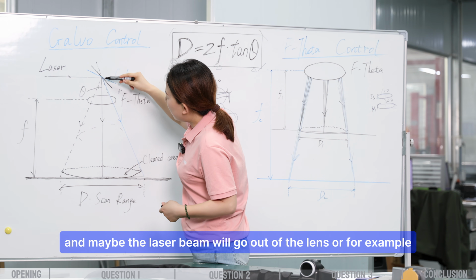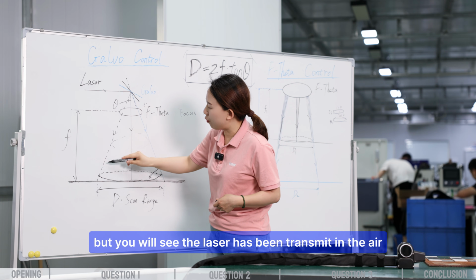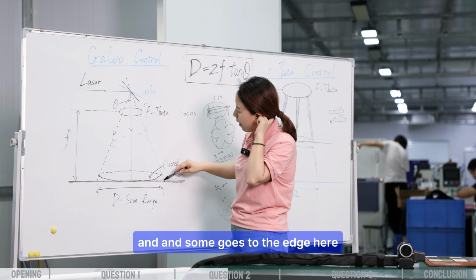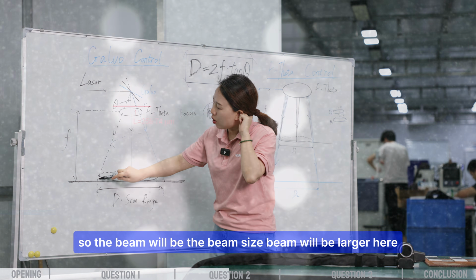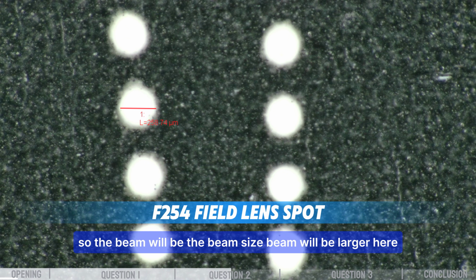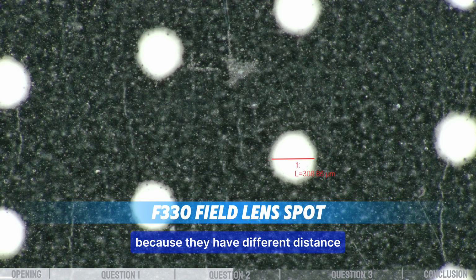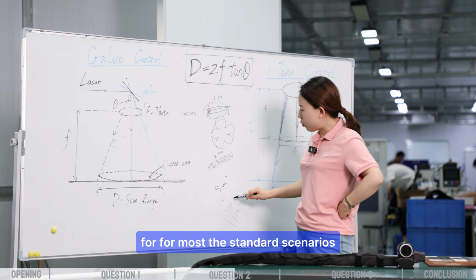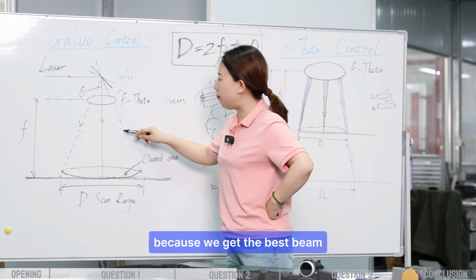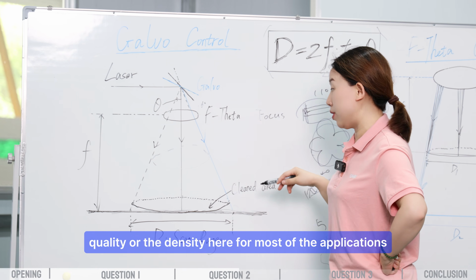Or, for example, you will see the laser has been transmitted in the air for a longer distance, and some goes to the edge here. So the beam will be larger here and smaller here because they have different distances. For most standard scenarios, the standard lens is okay because we get the best beam quality or density here for most of the applications.